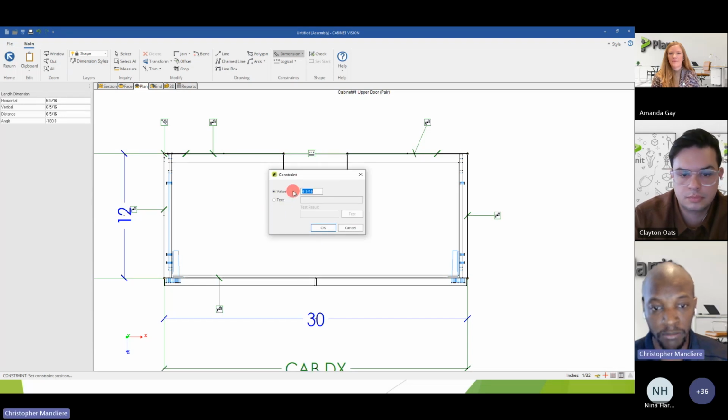So this one I can just type a fixed value of 8, because in my example it will always be the same. But if you are a little bit more advanced and do some object intelligence and add your own parameters, you can add an option on the left side where you can let the user input the value of the width and the depth of the notch.